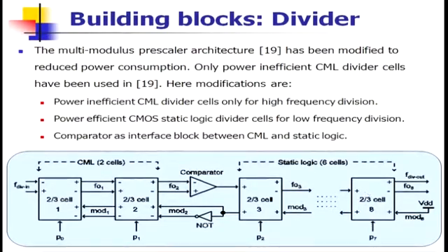So, here my frequency is 600 megahertz. My assumption is that static logic will work at a magic figure of 674 megahertz. So, I said that okay, after 600 megahertz you go for the static logic, but before that you need a faster response, it will not work with standard CMOS. So, you will go for this; this is a 180 nanometer kind of realization at the time. So, we go for this.